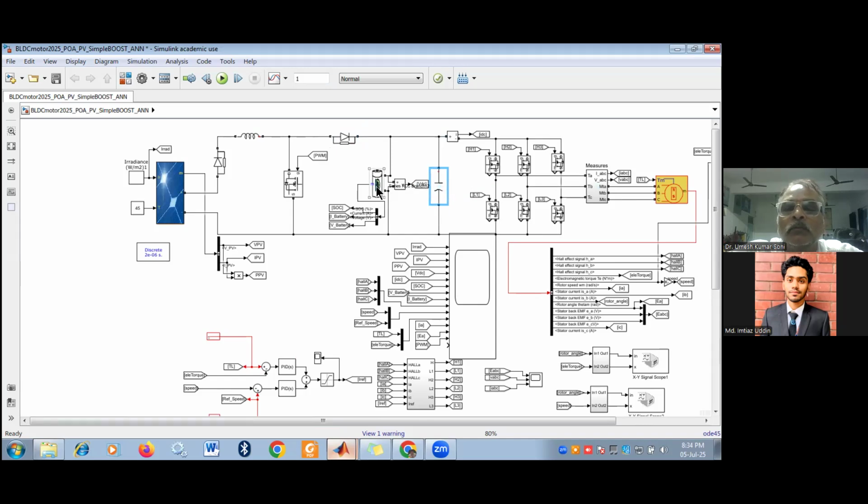Here we have the battery energy storage system. The battery energy storage system has three main parameters: current of the battery, voltage of the battery, and state of charge. In the standard case, the battery should not go below a certain state of charge limit, and it should not exceed about 90 percent. So it should be within some margin so that its life is better.